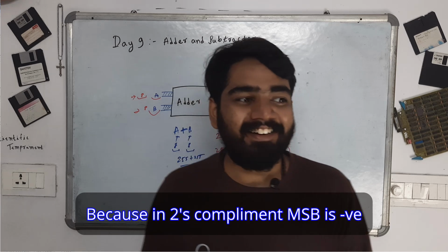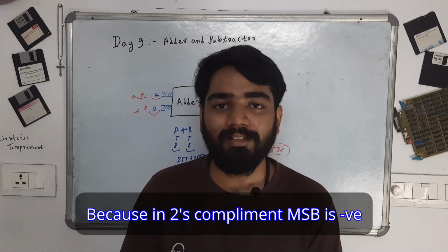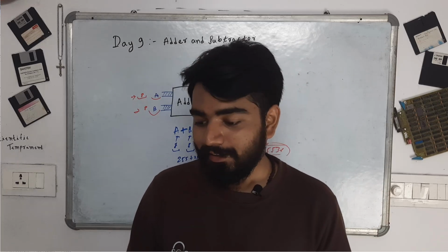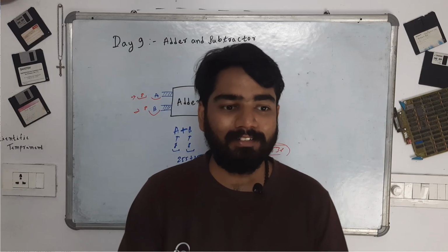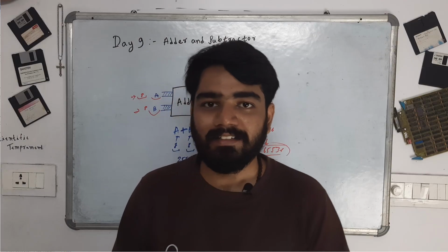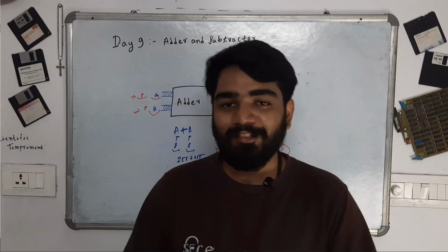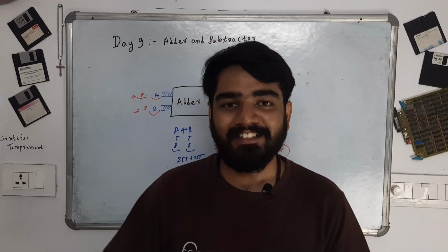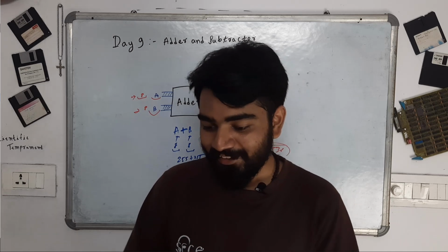That's the thing, right? This is a very tricky thing to handle, signed and unsigned numbers in Verilog, and we often face this issue. We see signed overflows all the time when we do FPGA projects, right? This is one of the main things you need to keep in mind. Everyone faces this when they are doing FPGA projects. So I'm telling you from the start, please keep this in mind.